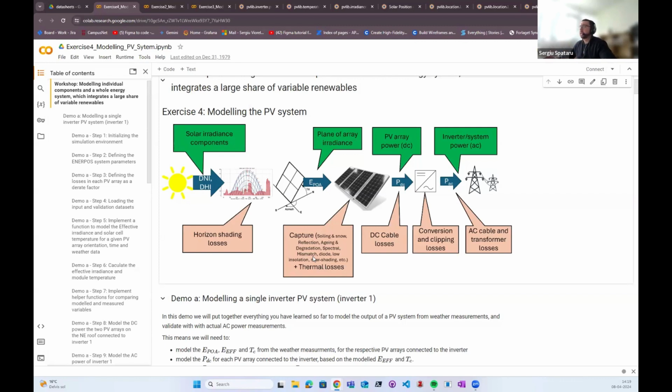So if panels degrade at different rates, the voltage and current will not match with each other anymore, and then the MPP power tracking will not be optimal, and you have overall a lower efficiency of the array as opposed to the efficiency of the individual panels. Then you can have losses in the diodes as well,